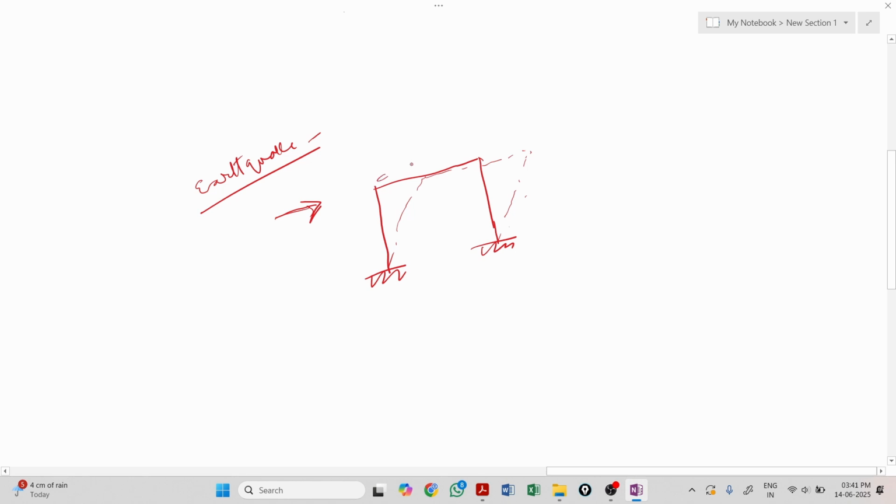And due to the sway, there is a load, that is W or mass, and this is swaying, and there is a length in here, I mean this whole thing length, and due to that there is some kind of a resistance force from this side. That is correct. That is base shear. When the force is acting, F is equal to ma. When the force is acting, there is a mass and there is acceleration happening. That is inertia force. This inertia force is happening due to this mass.